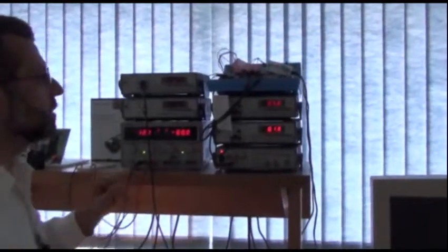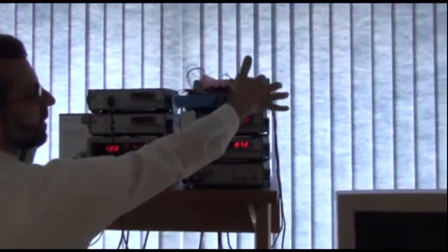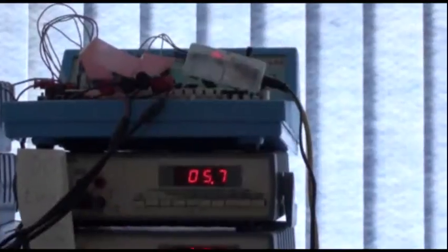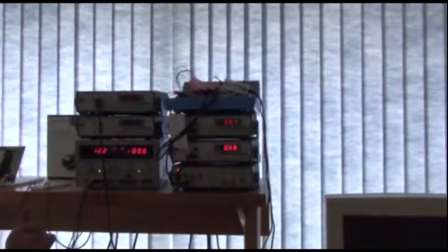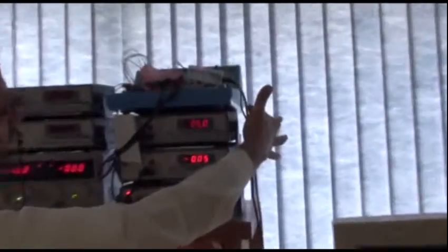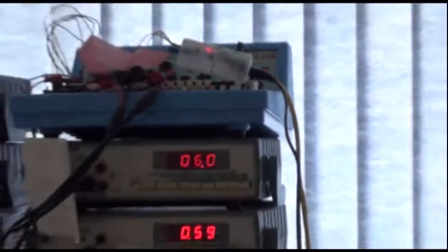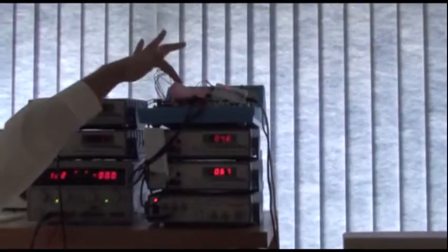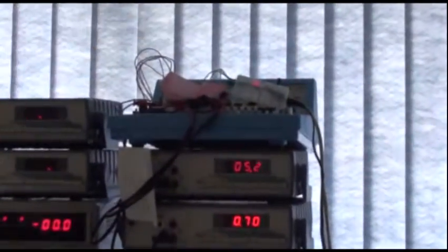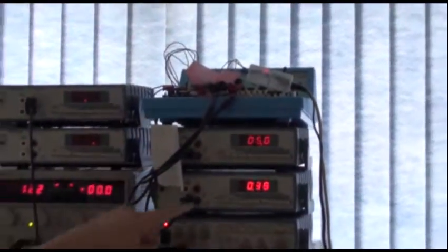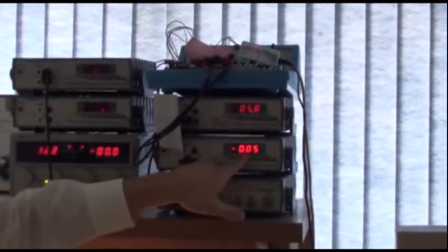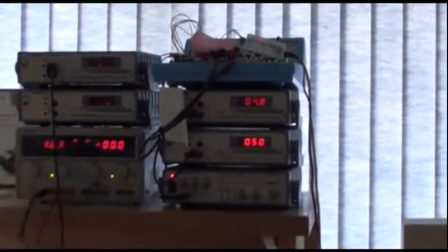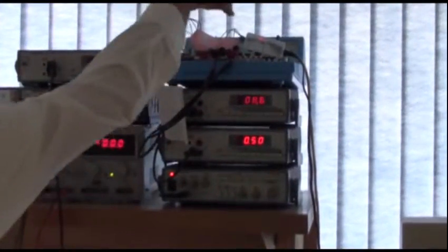Another experiment I can show you here is I'm using the same embedded system building block, which is again a full controller and an embedded web server as well. It connects to the Ethernet directly and a 9-volt supply, and then all the IOs are connected to it. This circuit is exciting a transistor that's being tested for IV characteristic. So sequentially we apply a sequence of currents on the junction and we read the voltage drop, and then we draw the IV characteristic. All of that is done right here in this box.